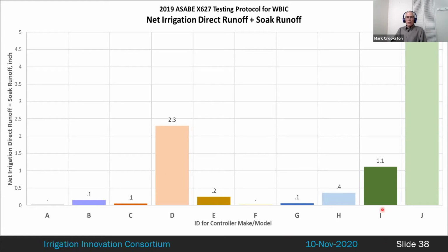The weather service for controller I, that company has its own weather server to provide rain and ETO to its controllers. That controller changed companies, and in that transition, the weather server was allowed to go offline towards the end of the testing period. Normally, I would have expected controller I to do much better, but without good rainfall and weather data, it had to rely totally on historic averages.